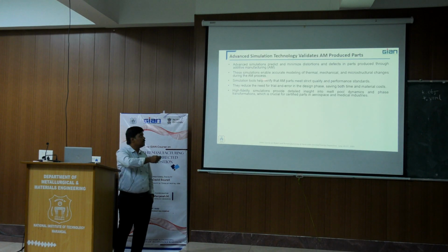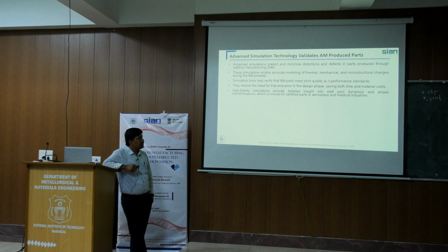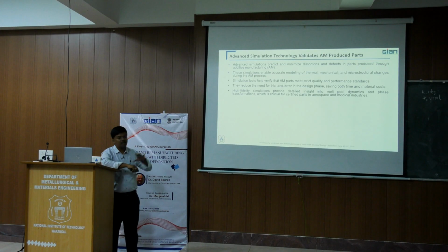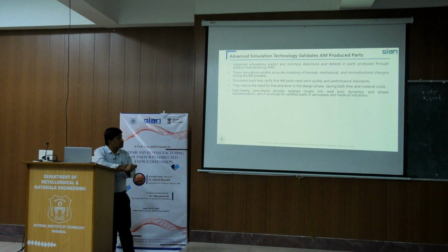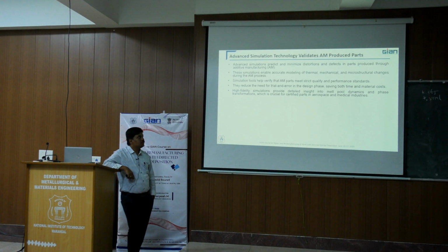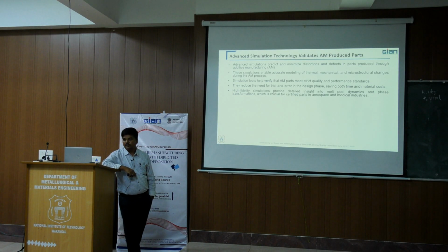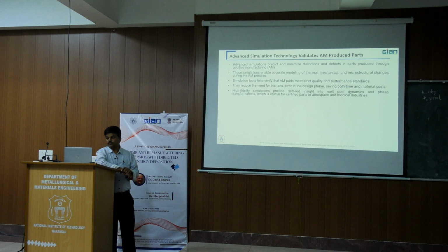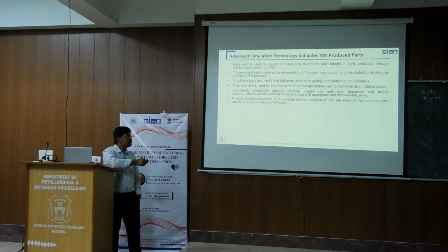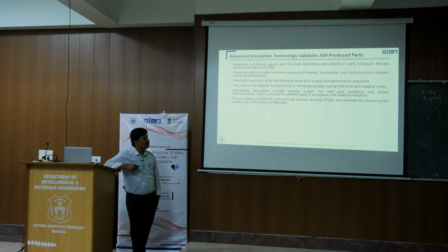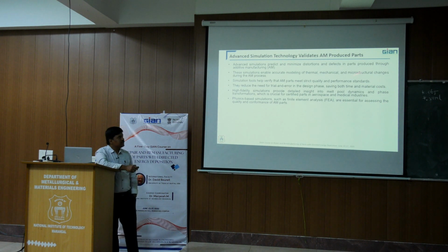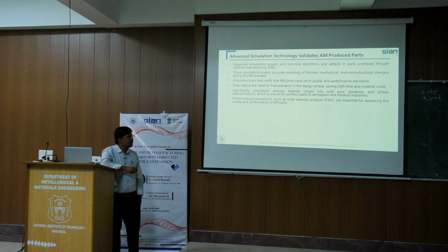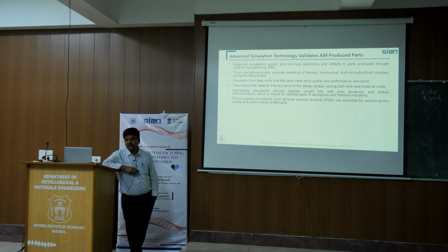And the high fidelity simulations will provide detailed insight into the melt pool dynamics as well as the phase transformation, which is crucial for certified parts in the aerospace and the medical industries. And the physics-based simulations, because we might be doing FEA with ANSYS and all, are very much essential to assure the quality and conformance of our manufacturing.